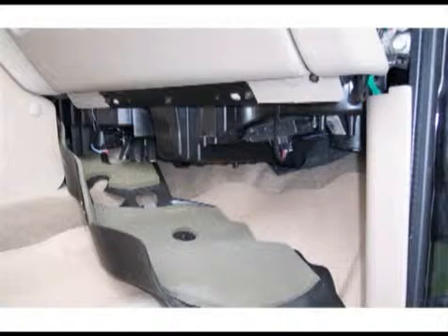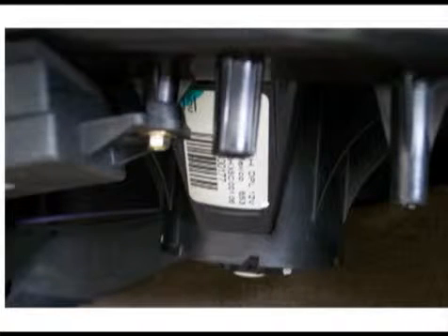We have confirmed that we have power to the blower control module, so we're going to remove the hush pad from under the instrument panel on the passenger side and access the blower motor. We merely reach under the panel, depress a little spring-loaded tab, and twist the motor counterclockwise. We remove the motor from the HVAC control panel and we take a fuse jumper for power and ground and apply directly to the motor. The motor performs well on high speed with power and ground applied.